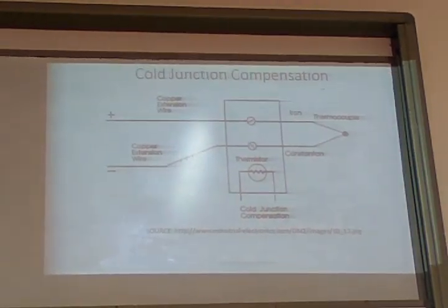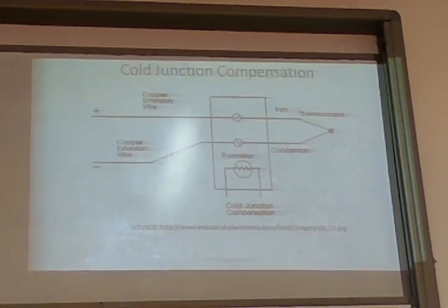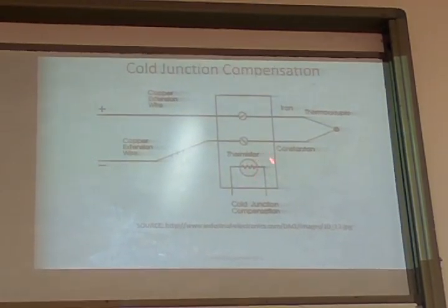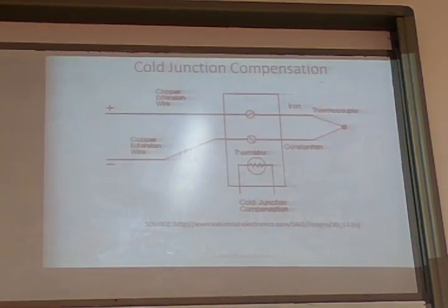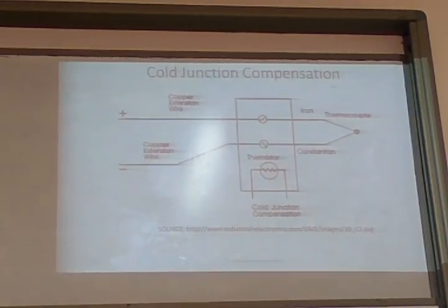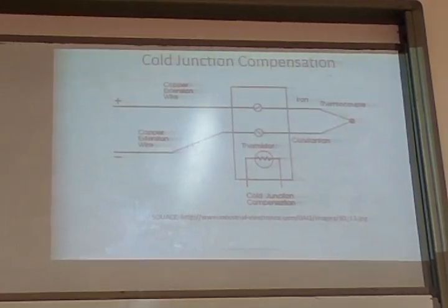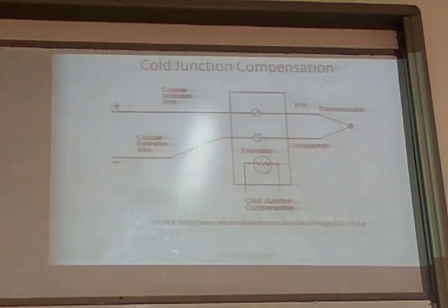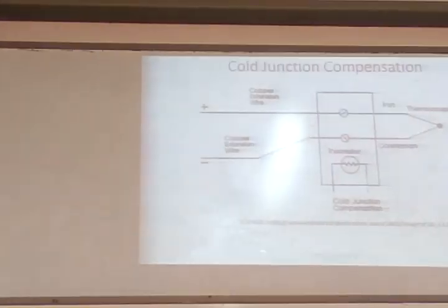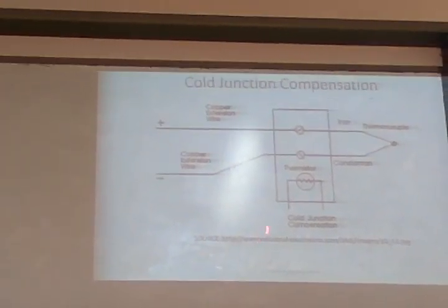We have a thermocouple measuring setup in our lab. We don't use an ice bath. You can go and see. We use another sensor, typically a thermistor. You can get a thermistor for 50 or 60 rupees. Of course, the corresponding signal processing you can also do for 100 rupees. So 3-4 resistors and some voltage that you get from another supply. Less than 100 rupees, you will be able to do the entire temperature measurement using a thermistor.